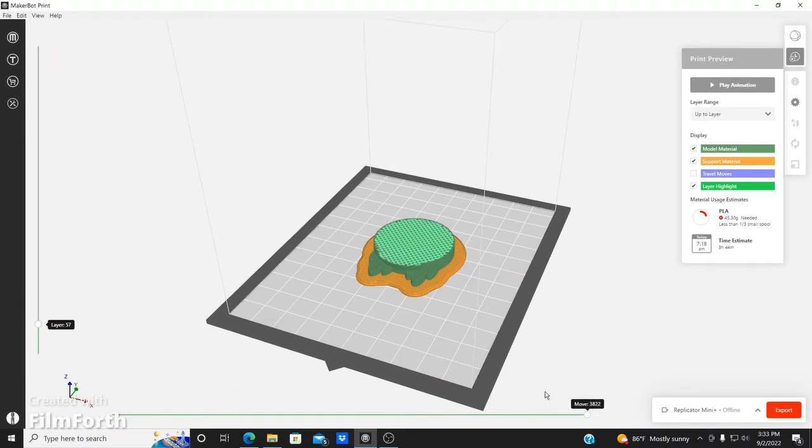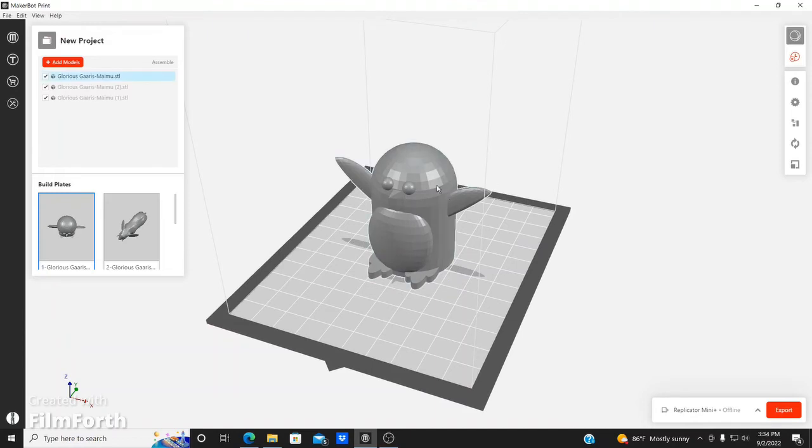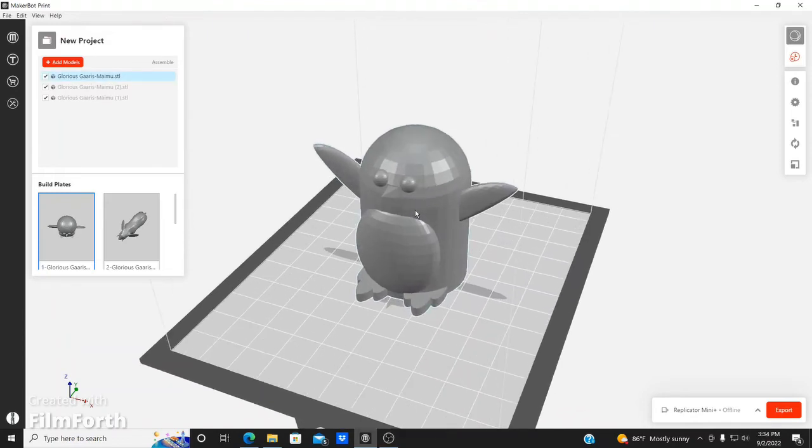It will break apart every now and then. If you want to ask why it's not starting from here and over there, again, it depends on how you do your settings and what type of slicer software you have on your toolpath, or you have to change it in your CAD software to generate the toolpath correctly. That way you prevent it from doing this right here, where it starts randomly anywhere else around here rather than just going from start to end. So that's the reason why you have to do certain slicing, and there are certain softwares that require that. Okay, now remember that one, the 50% infill and the raft.